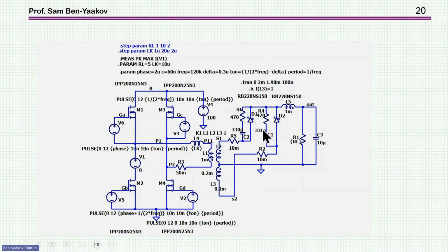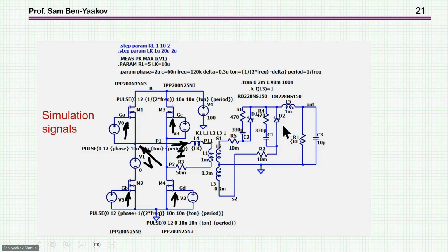And then I have here two diodes, and I've put a snubber to damp some oscillation due to the capacitance of this diode and the secondary. And here is the filter. This is like a regular full bridge PWM converter. So I'm going to show, first of all, these pulses here, the gates, and the voltage here, and the current. So here it is.